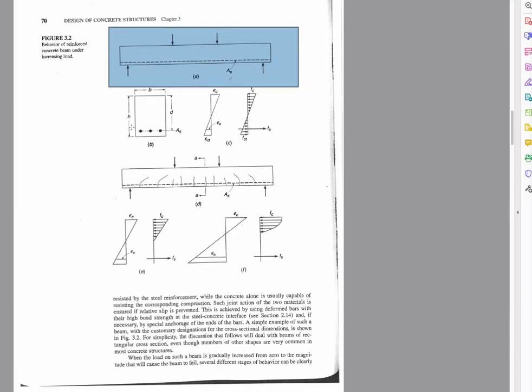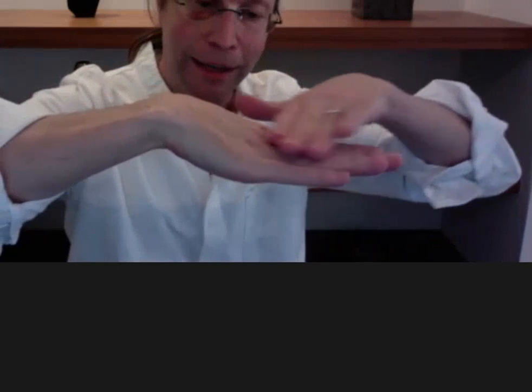And it's shown here acting on the bottom for good reason, that this is an example of conventional flexure. And the flexure that we're speaking of here is something like this. So it's a beam that is going through loading that would bend it like this. And if you do this with your hand, you're going to find that the skin on top of your hand crinkles up, and the top of your hand is in compression, just like the concrete in that beam. The bottom of your hand is getting stretched, and you can feel it in the skin.